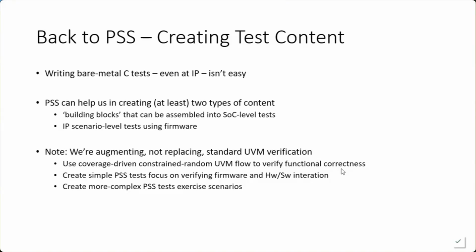We're creating the PSS content here initially primarily as a way to verify the low-level driver firmware and the reusable PSS elements that we'll hand off to the SoC team. We can create some more involved scenarios with PSS at the IP level, but that's not really the primary point here.